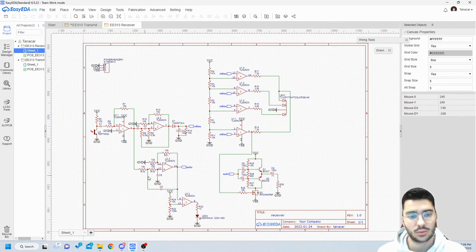And then from our original signal, we also extract our audio signal with a low pass filter design. We have already filtered the lower part below 150 hertz. Now we filter the high frequency reference signal. This filter has a corner frequency of 3 kilohertz, so we only get our audio signal.